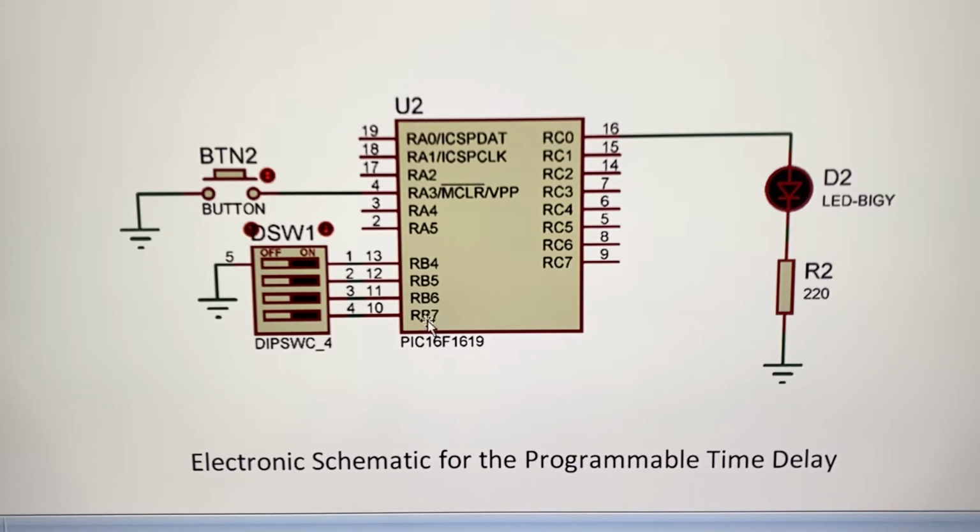We have to shift these 4 bits, or swap this nibble, and put it in the correct positions in another register or in the accumulator, so that the numbers have the correct binary weight of 1, 2, 4, 8. Because as you can see here, the binary weights will be 16, 32, 64, 128, and we don't want those binary weights. This is why we have to move or swap them to the correct position.